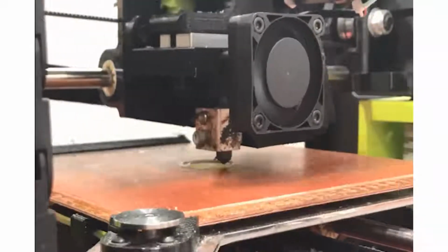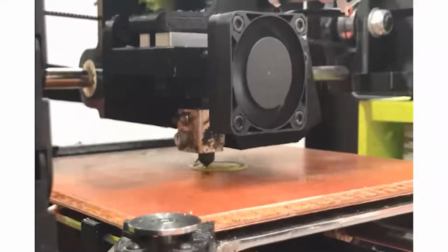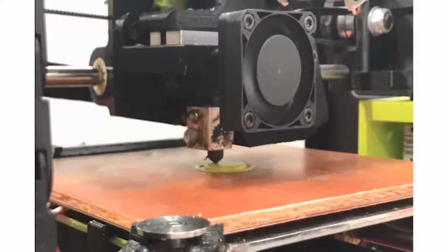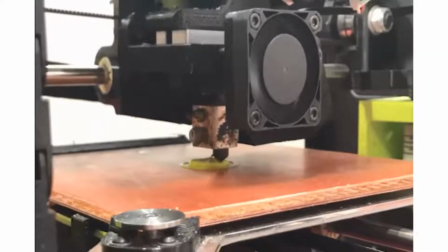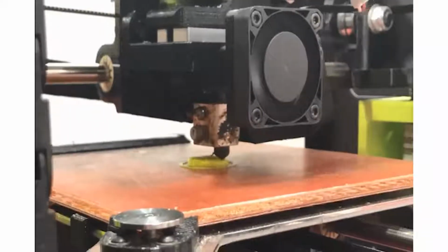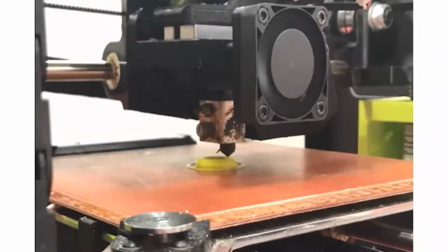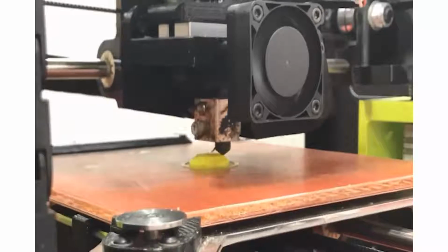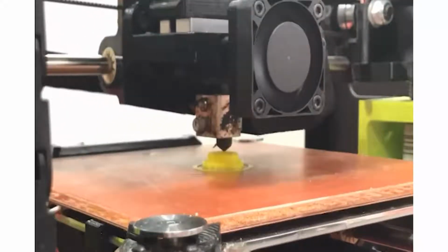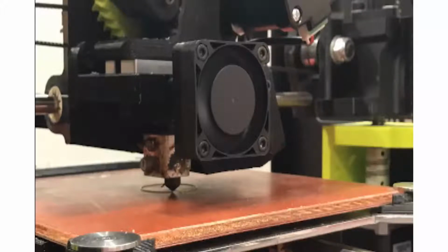Our original idea to use a 3-blade fan didn't turn out as well as we'd hoped. We had to resort to other ideas to generate enough wind power to make our bubbles detach from the CD. We tried everything from cardboard blade fans to 3D printed ones, and nothing seemed to be strong enough. What we eventually noticed from the patents of previous bubble machines was that centrifugal fans allowed for plenty of airflow and a concentrated air stream. So we got to the 3D printers and made it happen.